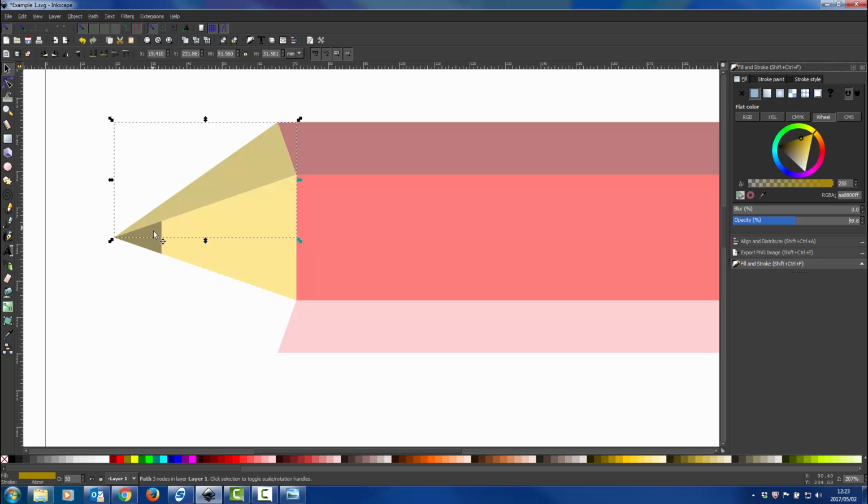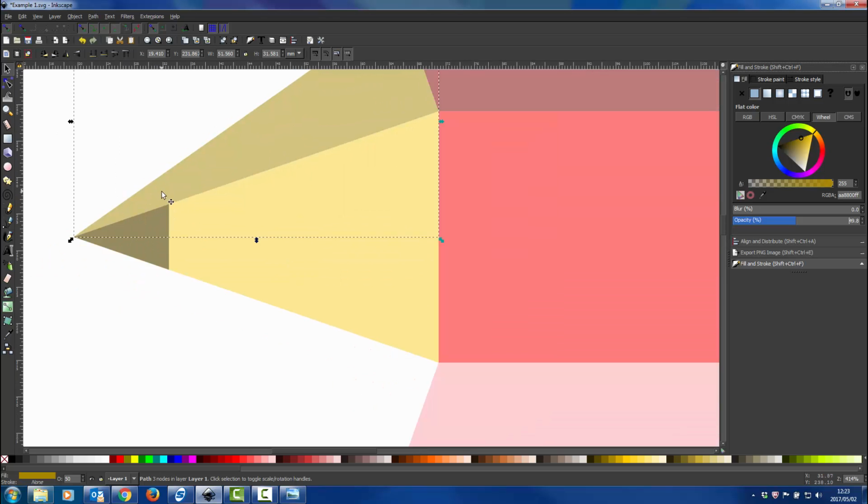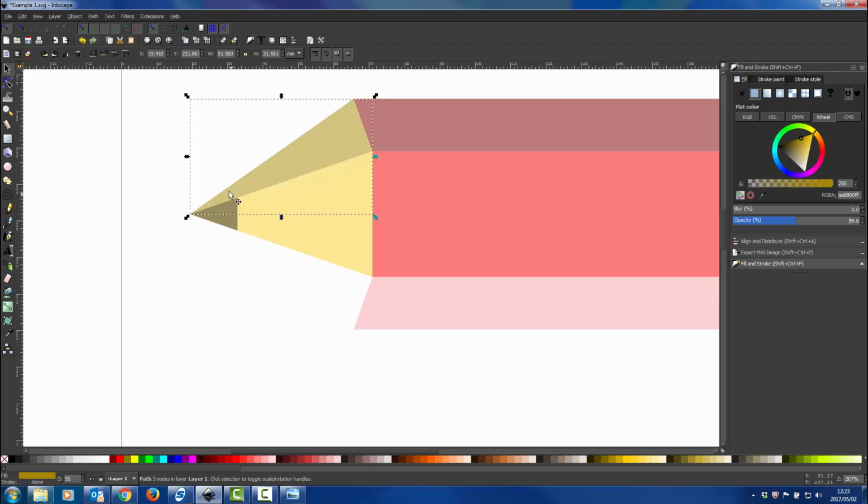And then I also want my little graphite tip over here, and I want this line to line up with this line. So here I'm going to use the trim function that I showed you earlier. So I'm going to duplicate this once, and I'm going to change it to a dark color. And then I'm going to duplicate it again, and this is going to now serve as my cutting plane. Let's make it something completely different, green for example.